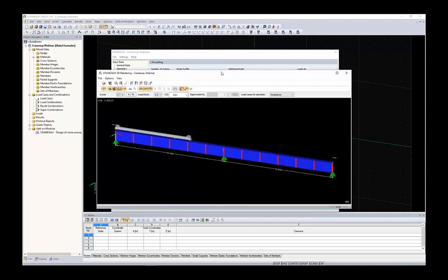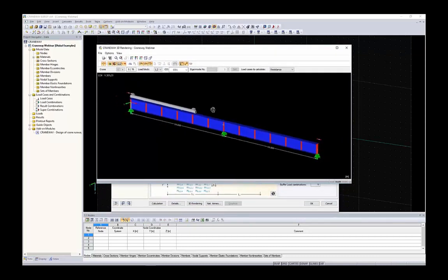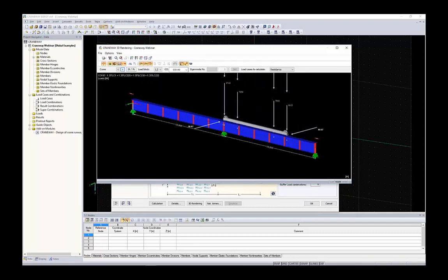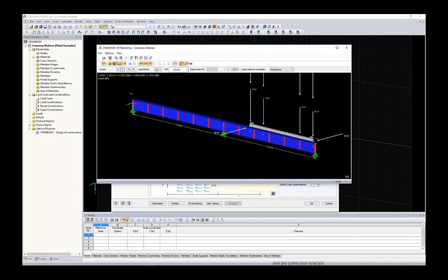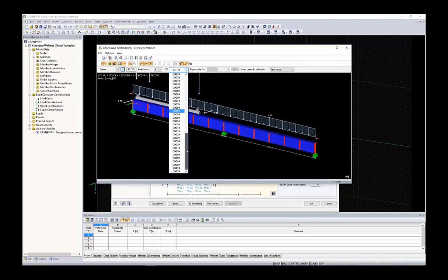And what does this mean? You can take a look in the graphic, the 3D rendering over there, and there you can check the definition of the crane. We have 4 crane axes with these 2 meters over there, 5.6 and 2, and this is basically the calculation which is done later when you press the calculation button. The program will calculate all the load positions, load blocks and combinations according to Eurocode 3.